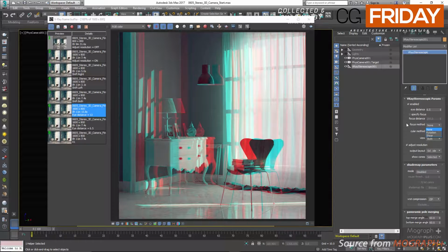When set to rotation, the stereoscopic effect is achieved by rotating the left and right views so that their focus point coincide at the distance from the eyes where the lines of sight for each eye converge. We have shear. In this mode, the orientation of both views remain the same, but each eye's view is sheared along Z so that the two frustums converge at the fusion distance.